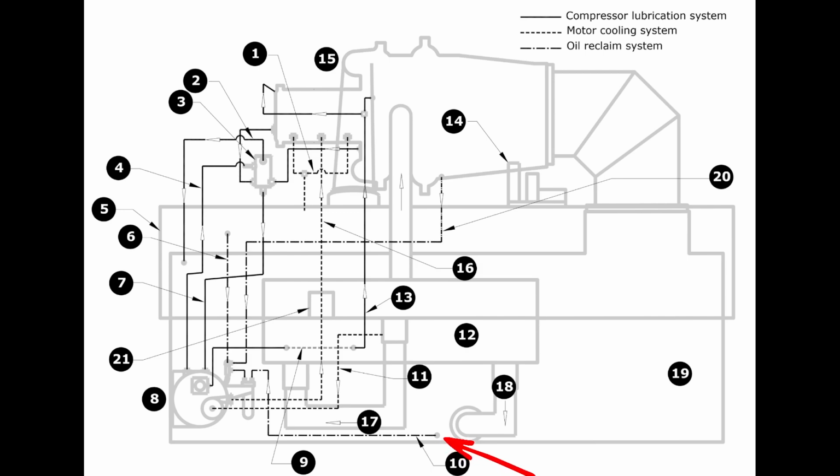All the training I've had on this goes back to you've either got a sight glass or you've got other symptoms, like your temperature and pressure in the tank. If this is having issues, or if you're freezing up on your filter lines, then you're sending a little bit too much liquid through there, and you need to back this down to send a little less so it's not able to freeze like that. That's one of the symptoms.